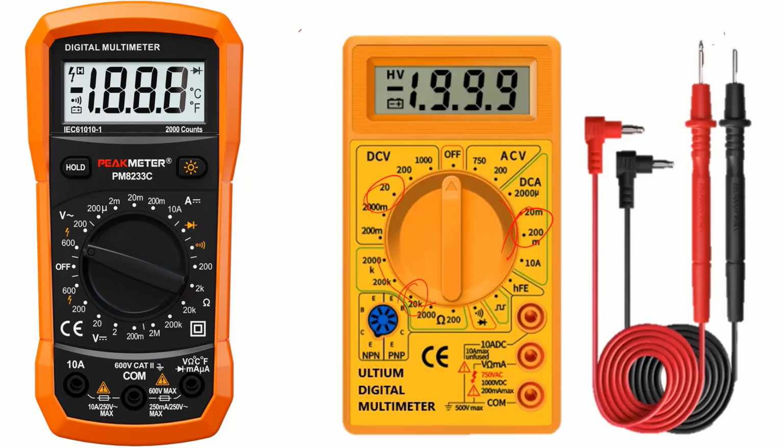And don't forget, your plugs can vary. So when the black is fixed on the COM plug, then if you are measuring little current in the order of milliamperes, the red should be here. If the current is too high, you put it in the 10A DC. Confirm. If you are measuring resistances, you can leave it there, and voltages, it can remain there, no problem. So that is how you use a multimeter typically. So connecting it now to your circuits is no longer a problem.